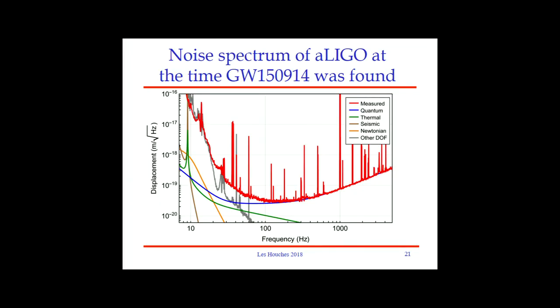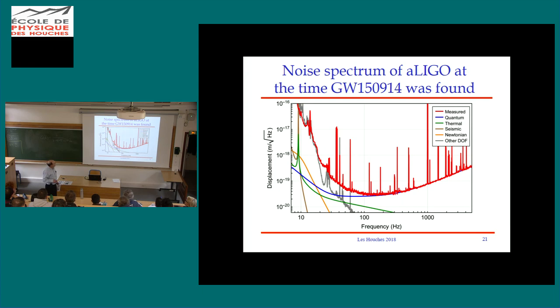All right, so let me show you where this ought to all come out. On this noise budget graph, and remember, this is an amplitude spectral density in displacement units, meters per root hertz, in a logarithmic scale versus a logarithmic scale of frequencies, and here's 10 hertz, and seismic noise calculated as the input times the frequency response of the system is coming down very steeply and doesn't quite meet the spec at 10 hertz, but by 12 or 13 hertz it does. Okay, and furthermore, you can see that it may never be the dominant noise source anyway. This is really sufficient seismic isolation. So there it is, and the steepness there comes from the many stages cascaded together.